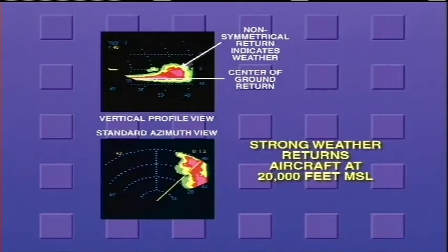When 40 nautical mile range is selected, normal ground returns appear out to 25 nautical miles. At 20 nautical miles, the radar shows an area of isolated precipitation between the aircraft and the major storm, which starts at 25 nautical miles. The roll cloud is a fairly typical phenomenon associated with severe weather.